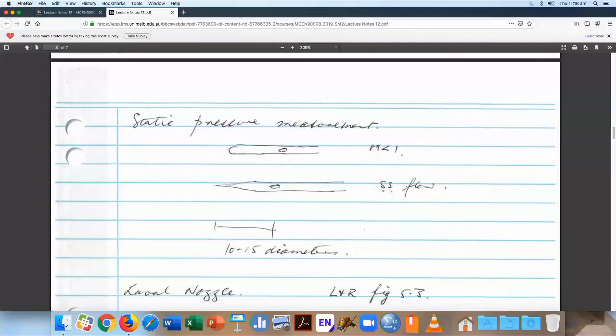So if we turn the flow just a very small amount, with an object that looks like this in supersonic flow, we turn the flow here through a shock wave, and then expand the flow out here through an expansion wave. You can guess that a very weak compression and a very weak expansion are all isentropic. And so this will be an isentropic relationship here.